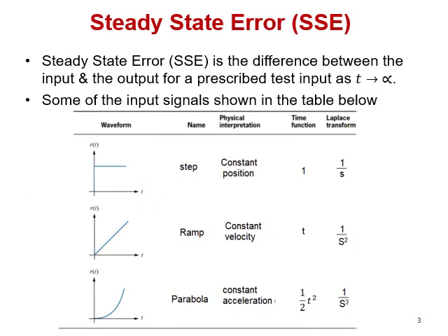Before we go through the steady state error, let us know that there are 3 types of inputs that will be sent to any control system for testing. They are the step, the ramp, and the parabolic. So any control system will be tested against these inputs. In Laplace, the expression for step is 1 over s, or the number of step over s. Then for ramp, it's 1 over s squared, and for parabolic, 1 over s cubed.